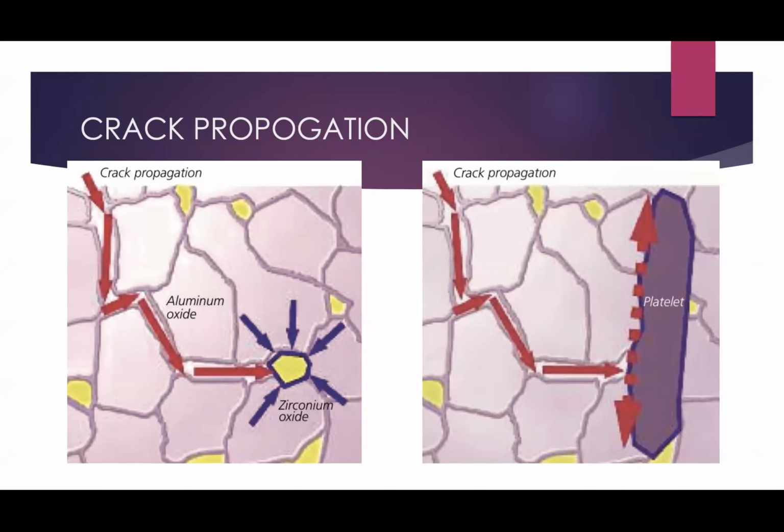So the first is this thing called conversion reinforcement. Effectively, the zirconium oxide particles act as an airbag. So when you bash the ceramic, it's like crashing your car. The impact gets absorbed by the zirconium oxide, which stops it from propagating, okay? And that means that basically the forces are homogeneously distributed throughout, and so you don't get this crack propagation.